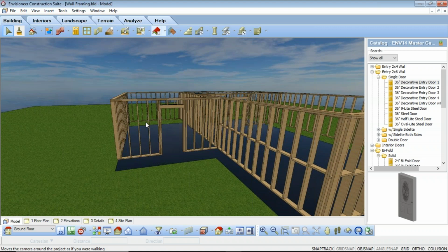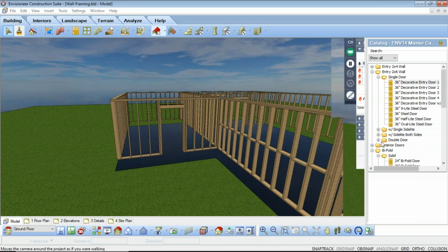Your location framing options include a span table selection for load-bearing walls and one for non-load-bearing walls. You can add and edit span tables to ensure your openings are framed the way you want. Framing mode allows you to override the location framing options and specify custom settings for individual walls, openings, and intersections in your model. So again, I'm going to go ahead and open up the questions section.